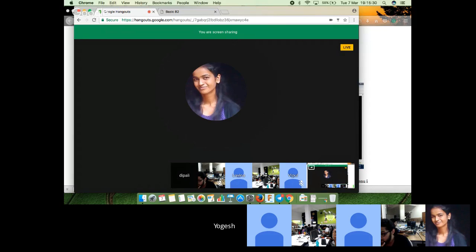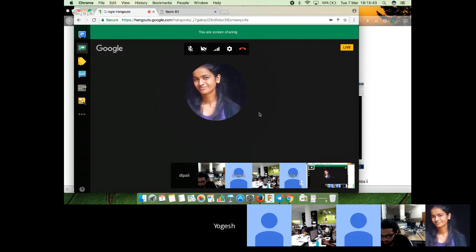Okay. So in the ATtiny44, have you selected the clock and fuse bits properly in Proteus? I don't think so. So how do we do that? Just double click on the ATtiny44 schematic in Proteus. Select the fuse bits. The fuse bit numbers you can get through the datasheet of whatever IC you're using.